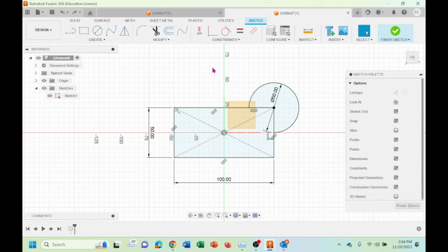So I'm coming back here and use the other modify tools that I have in the two-dimensional sketch. So how about the break? Instead of deleting that, first I break this and then I break this. Then instead of the trimming, I change this to the construction, which tells it that it's not part of my design, and see, somehow it works, right?